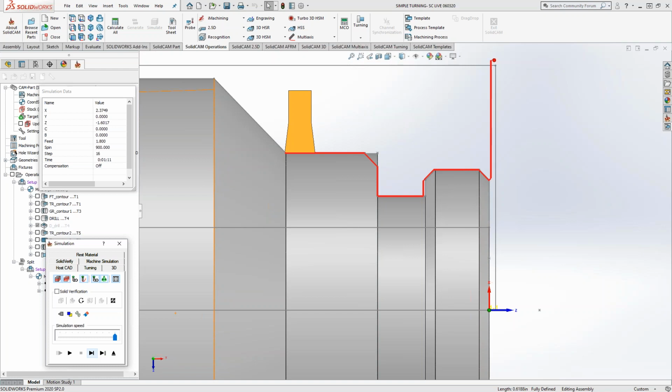So if you've got two O-ring grooves that you have to machine in one turn, and you've got a tool that can do both of them, really you're just going to define one of those points on that insert or on that tool, and then sketch geometry that follows a pattern that you create. So you actually machine it per your own trajectory, your own toolpath. That's basically what this is.